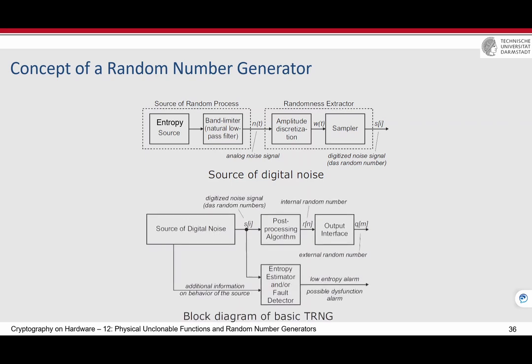Most of the time, there is an entropy source inside a device. For example, I can shortly explain. You have a voltage level, VDD, and it has a small noise, because for example at 1.1 volt, you can never see exactly 1.1000000 volt. There will be a fluctuation of, for example, 1 millivolt or even smaller.